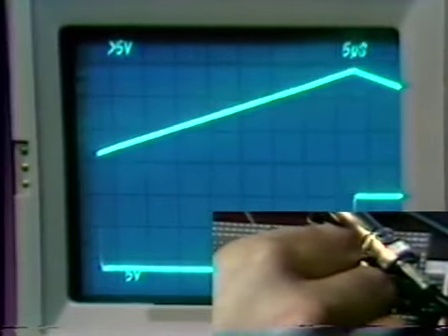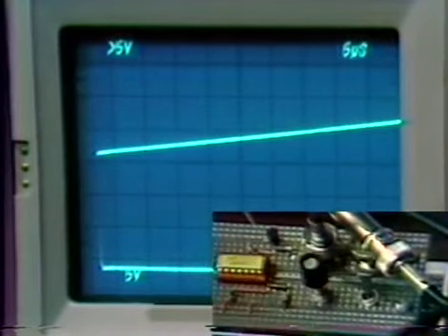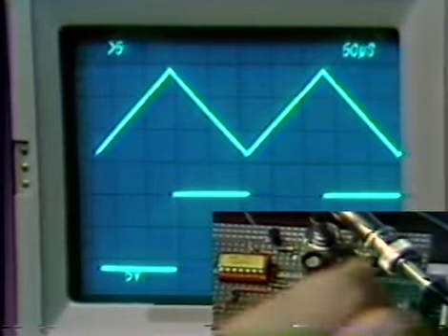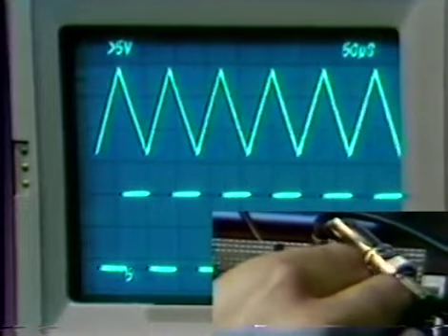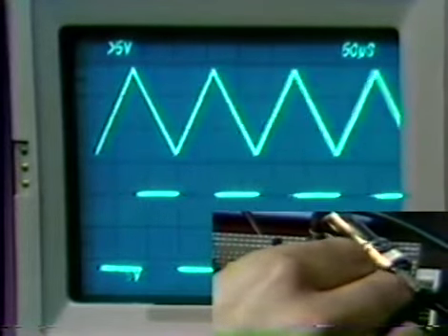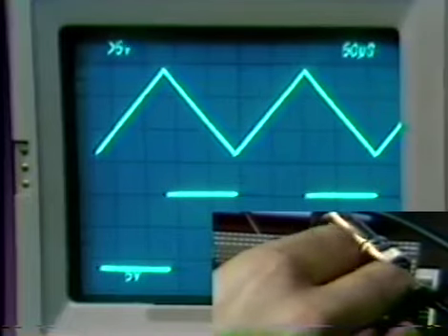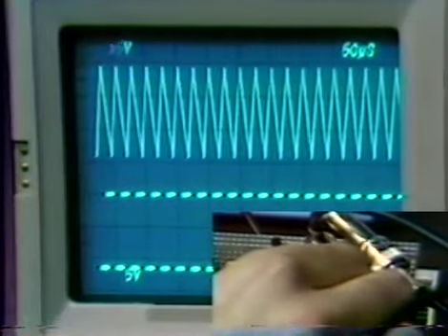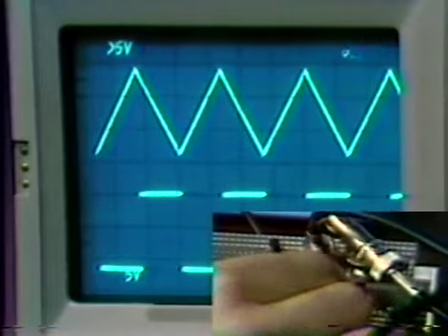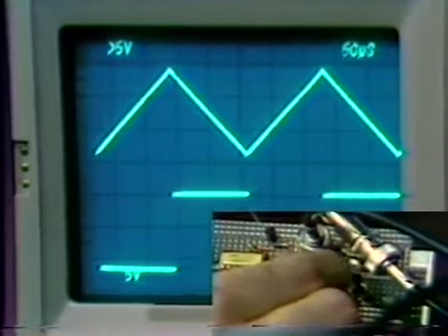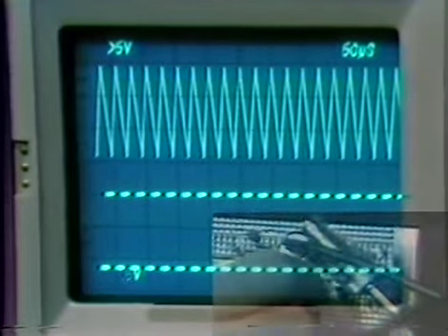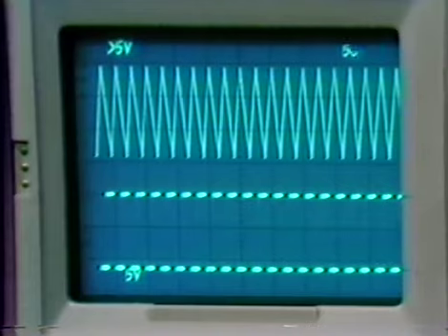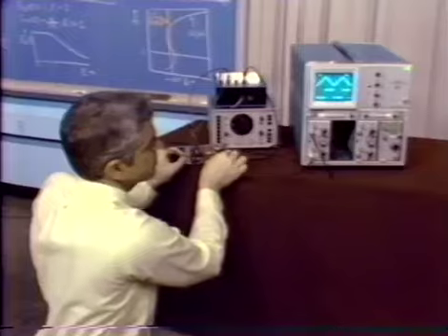So we're able to get very easily that sort of change in frequency by adjusting a single component and an easily adjustable component, a potentiometer, as opposed to an energy storage element that has to be tuned. And as I mentioned, then typically the capacitor will be switched in possibly decade steps in order to change the basic frequency of operation, something like this, where there are a series of decade steps available on the commercial function generator.